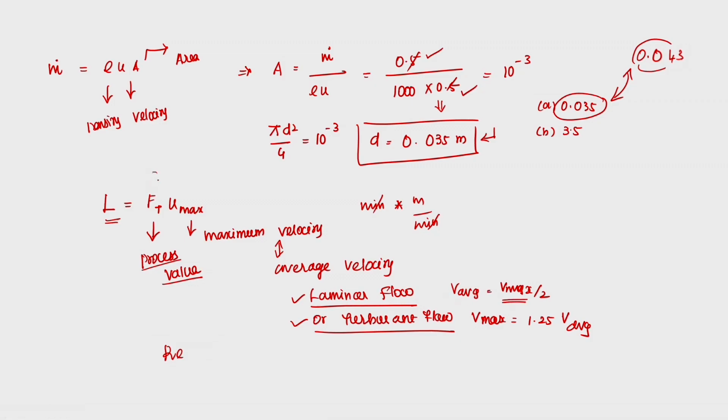Then after that I will substitute in the Ft value to calculate L, which is nothing but the holding tube length. So, Reynolds number here is D rho V upon mu. D I have just calculated, which is 0.035 into 1000 into 0.5 divided by 0.3 into 10 to the power of minus 3. So, which comes around 60,000. So, obviously this is a turbulent flow,